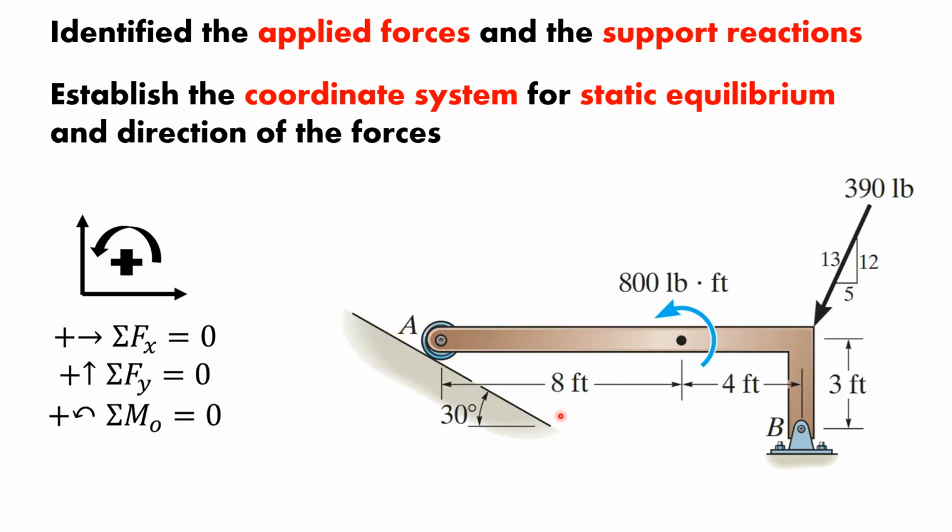So we can look and see how these reaction forces, the support reactions, are responding and how they're affecting what's going on with the body. And that's where the sum of forces in the X, the sum of forces in the Y, and the sum of moments about whatever origin should all equal 0, with their appropriate sign direction. So we're assuming static equilibrium. What this really raises is the question of what the appropriate support reactions are, and how do we handle that?